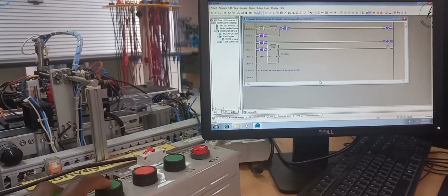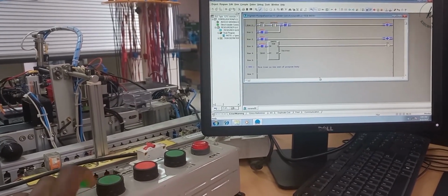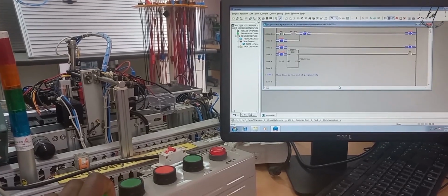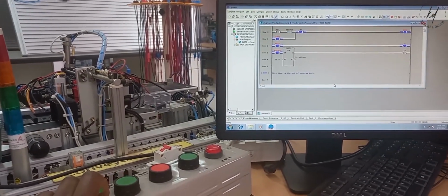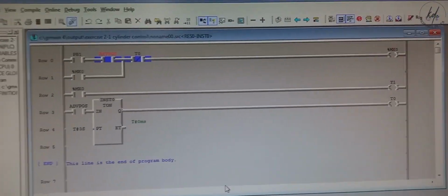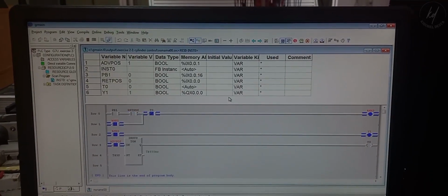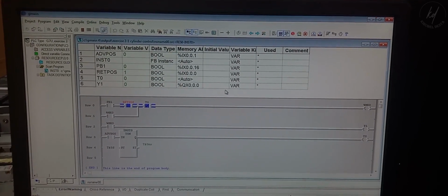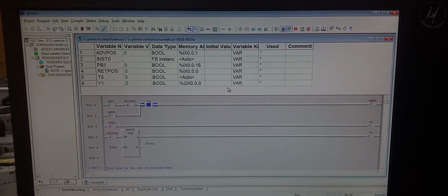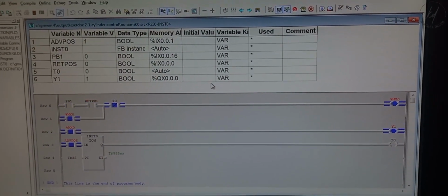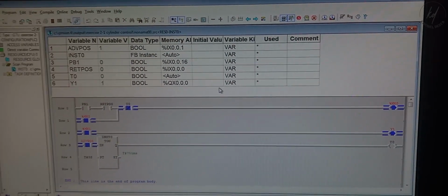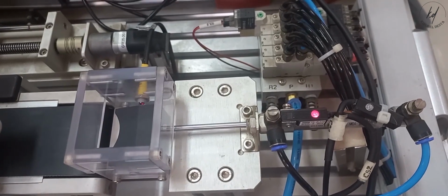As the start push button 1 is pressed, that would trigger memory address MX0 and self hold its coil and immediately advances the supply cylinder, and now the advanced state normally open contact enables the input pin of the on timer, so now the timer output pin remains off until its preset time, which is 3 seconds, is reached. Then this helps to de-energize the pneumatic piston and return it to the retracted state. We are able to see the ongoing process in a simulation manner on a serial monitor.